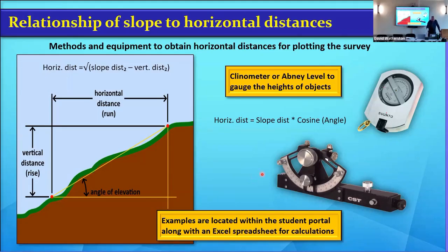And obviously, if you're up a hill and you're measuring left and right, you're not going up the hill, you're going left and right of it. Slope distance correction is probably not going to be much of an impact. You probably don't need to bother with it. But again, if you're in London, you're doing lots of stuff around London, the things you're going to come up against are walls, fences, hedges, or whatever. And you can use a ranging pole or a big stick with a spirit level on it, make sure it's upright, and then you can get somebody else to help you with the same at the other end and try and get the levels the same. So you get horizontal distance. Does that make sense to everybody? Yeah.